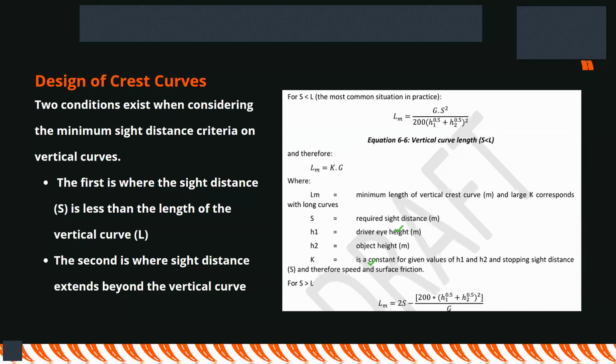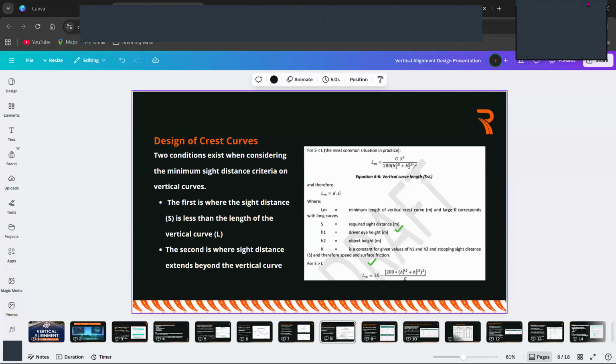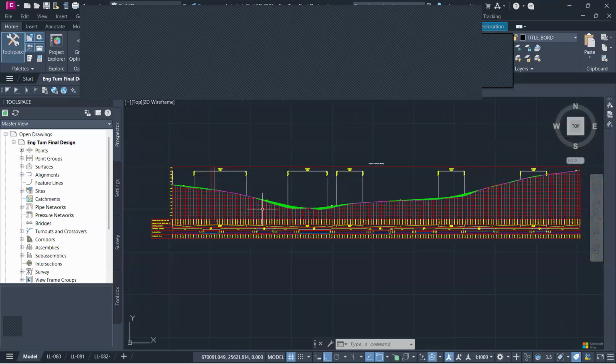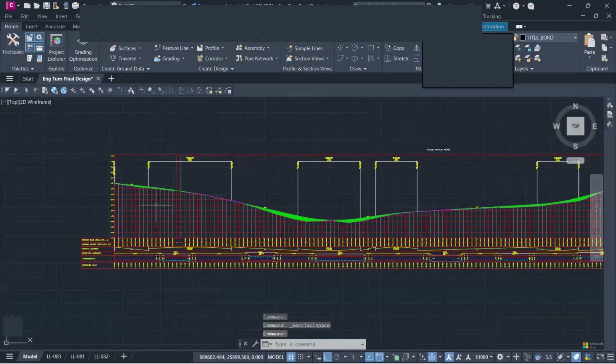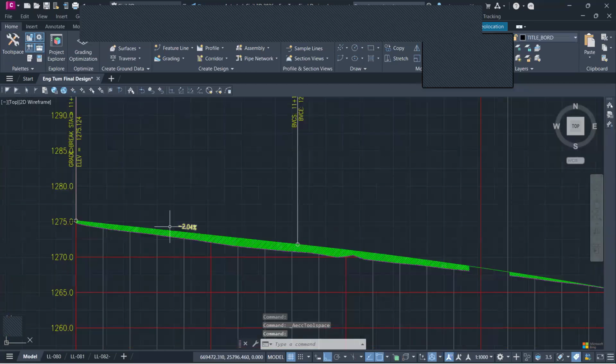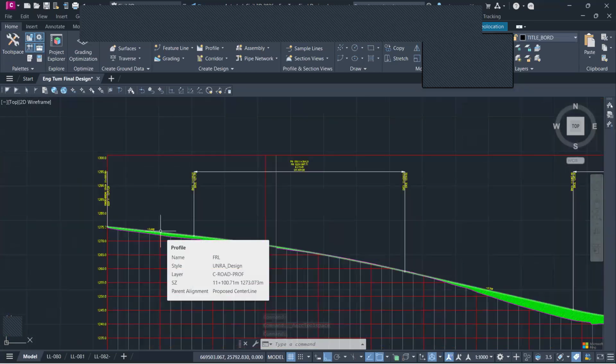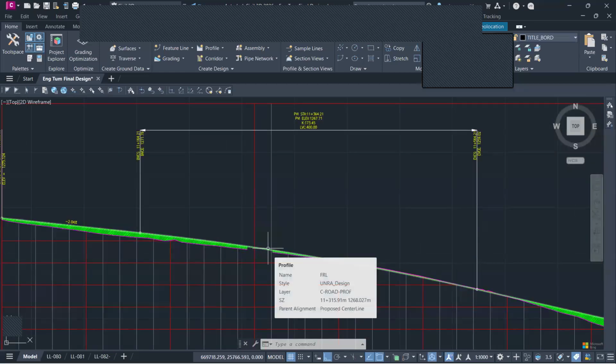So now I want us to look at the road design manual, because I don't want us to keep counter checking. This is a sample design for the vertical curve. Let me share my entire screen. I noticed that we are unable to see. This is another vertical alignment design. And as you can notice, this is the first section. This is what we are calling a straight gradient. And then after that, we have a crest curve here.